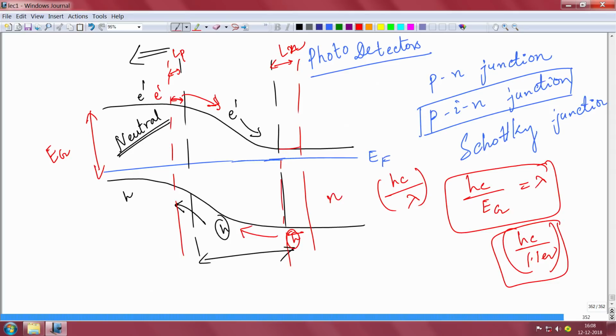Now, PN junction photodetectors typically do not have a gain, because this N region and this P region act as blocking regions that do not allow the carriers to either drift or diffuse across. So you can say that these are blocking regions, and so your gain is inherently 1, which means your photocurrent is actually your signal current, which is not the same in your photoconductive detector, if you recall. This will be given by your efficiency times the optical power divided by hc by lambda.